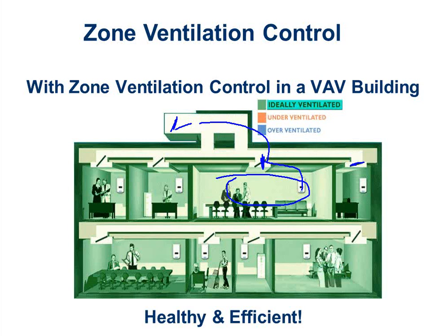So there's 2 numbers that you do with the code and you add them together. The entire reason that we switched the ASHRAE standards to the per person plus per square foot was so we can do demand-based ventilation systems. So the per square foot number we leave alone, and that becomes our base ventilation rate, and the per person number of the code we're allowed to modulate down.